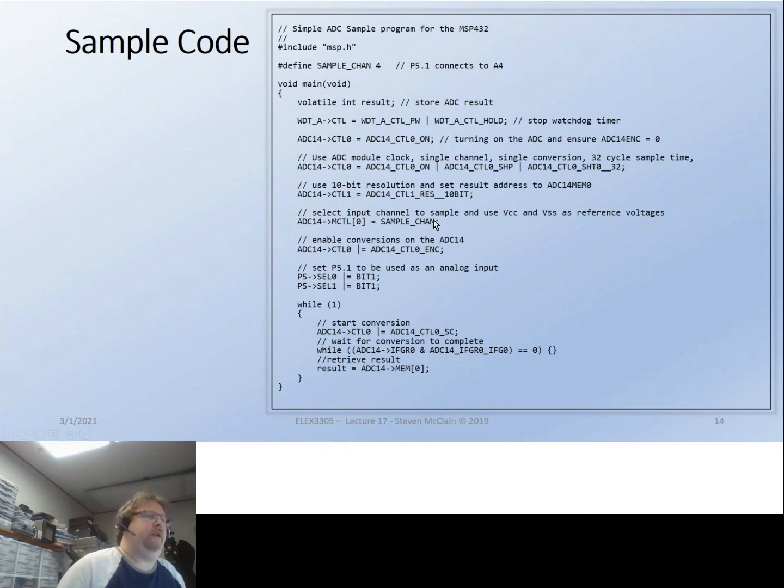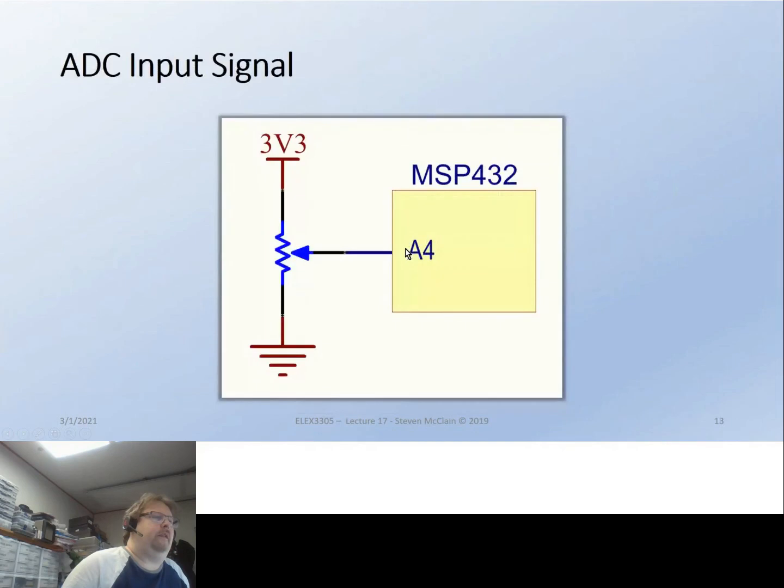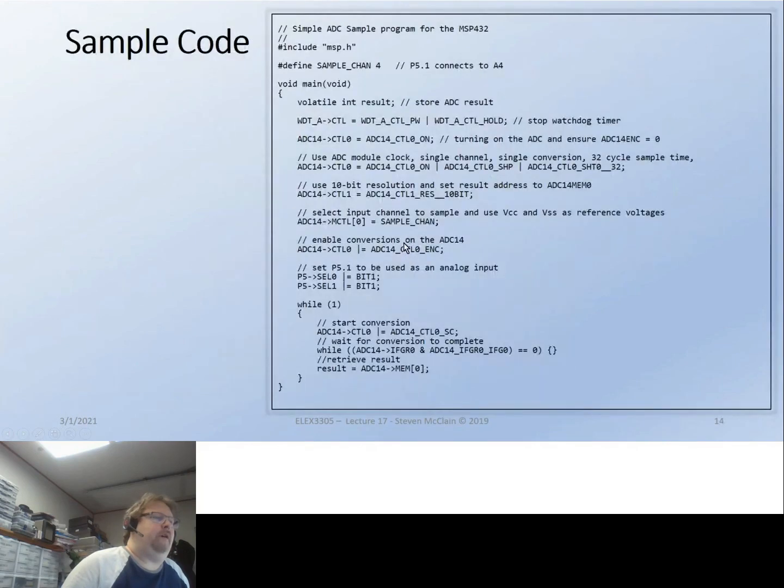So really, all you've got to write to the mem control is the channel number if you're only doing a single channel conversion, right? Okay. And then here we're actually letting the clutch out. This time we did an OR equals because we don't want to change the rest of the bits. We just want to set that one bit on, right? Oh, okay, I see the difference. We're just going to set that one bit on, where first we just said equals.